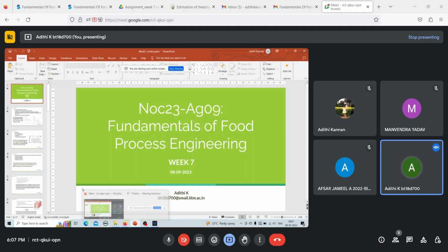So from this, now we can just directly substitute the values since all of the parameters are given. So density is 1050 kg per meter cube. L, which we now calculated as 274.7 kilojoule per kg, I'm converting it into joules, so multiplying by 1000. TF was minus 2.2 degrees Celsius. TA, which is the air temperature, was minus 30 degrees Celsius.